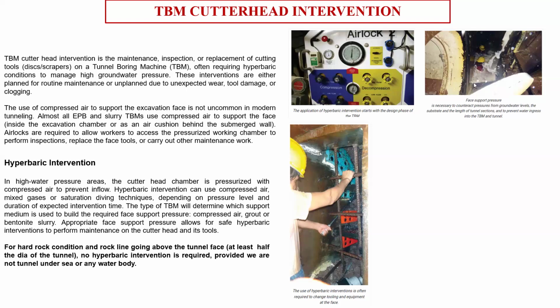So the method statement, the rectification, means he makes some additional grouting through the segment, either through the grout holes, or he tries to make additional holes, or he makes grouting at the interface of the segments, and whatever the gap is there, he makes it watertight by epoxy grouting.